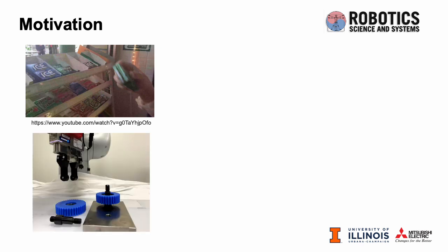To assemble this gearbox, a robot equipped with a two-fingered gripper may need to first reorient the parts and then grasp them. This problem is difficult as the algorithm has to reason about performing a non-prehensile grasp, rotating and/or sliding before the pick-and-place action. In this paper, we present a manipulation planner that is able to reason about diverse changes of contacts to discover such a plan.